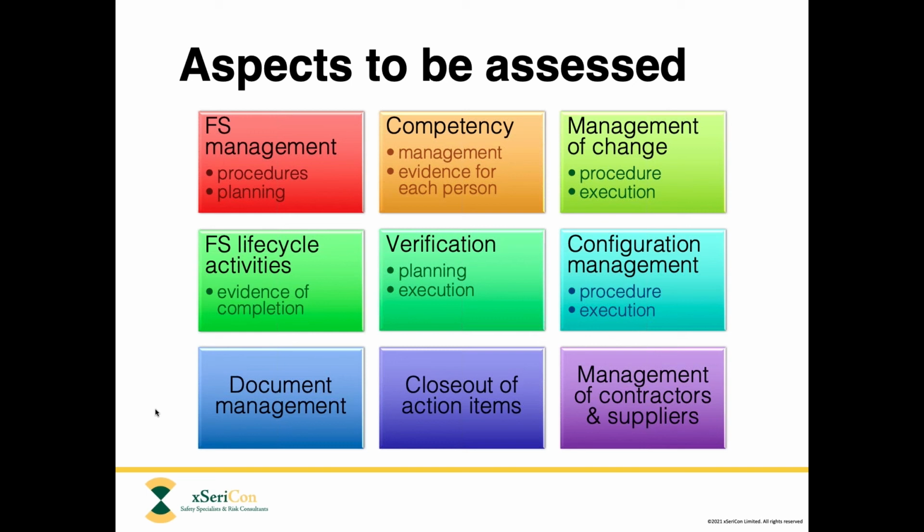The third area is relating to management of change. So once the detailed design for the safety instrumented system has been established, at that point, you should enter a management of change regime in which any further changes need to be properly managed and reviewed to confirm their overall impact on the system. So we want to see that there is a procedure for management of change, and we want to see that if any changes have been made, the procedure is being followed. So there should be some kind of documentary evidence that we can confirm for that.